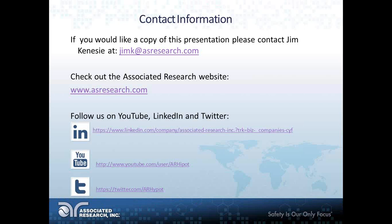I got one more, just a quick one, in reference to the scanners themselves. Are there any calibration or service requirements for that instrument? Again, we had a question about calibration and service requirements. Yes, we do recommend getting your instruments, including scanners, calibrated. You want to make sure your scanners are working within the specified range and according to the specs. So it is always a good idea to have these instruments inspected and calibrated yearly.